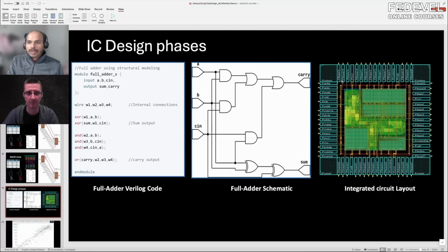Say if I want to connect, you see here the thin narrow path. I can connect it from here to here, or I could take this connection, go around, come back and connect. I can still do that. It is legitimate, and even from the manufacturing point of view it is acceptable.